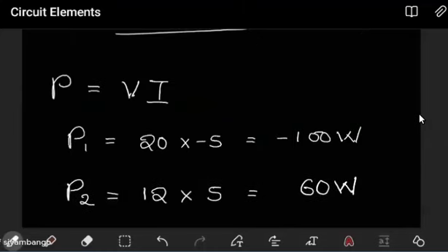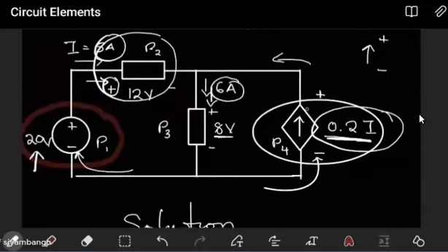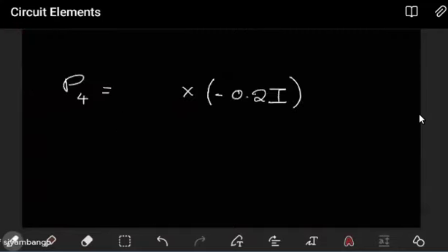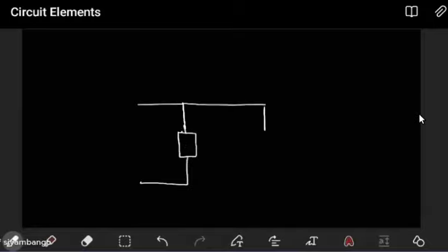So what is the voltage? That's the tricky part. We know the current source supplies current, but what is the voltage difference across its terminals? Here you have to recall the trick about elements in parallel. If you have two circuit elements that are in parallel, the voltage across them will be the same.